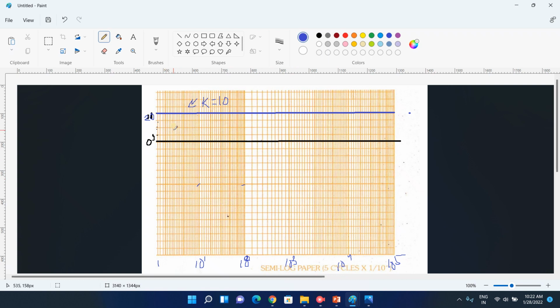That means for the numerator, if you have a zero at the origin, it goes from 0 to 20 in one decade, and it will travel in this same way. This is the slope.